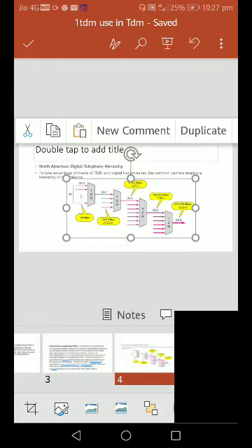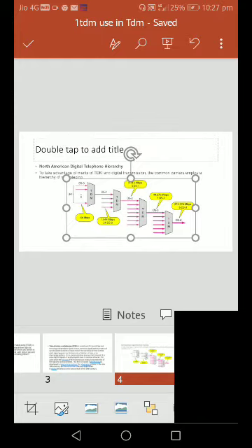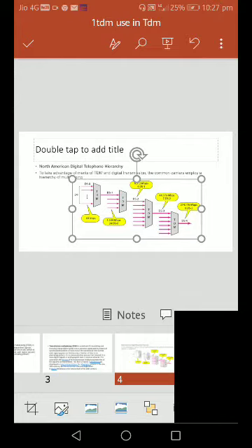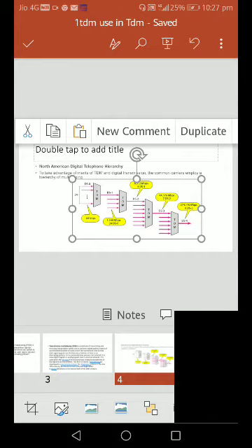We have to take the samples of the 24 signals. Each sample is 8 bits, and the sampling frequency is 8000. That is the standard for voice signals, sampled using the sampling theorem that we use in PCM techniques. PCM is pulse code modulation, used as the modulation.